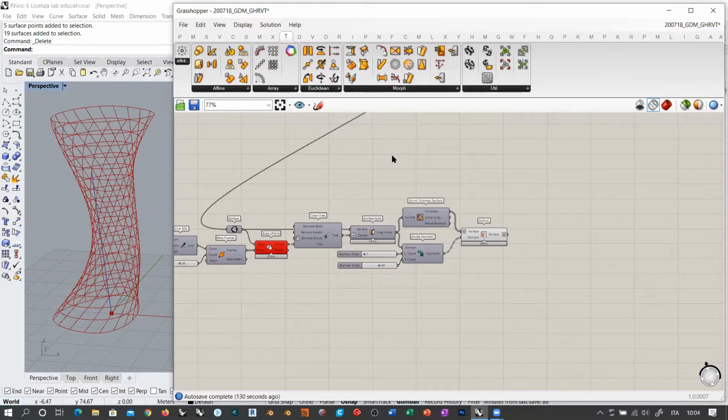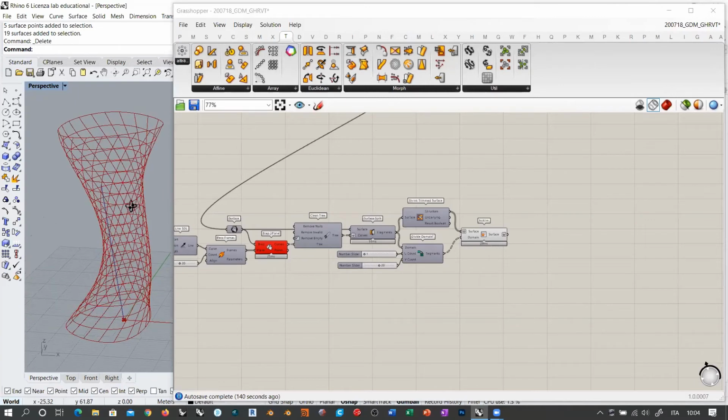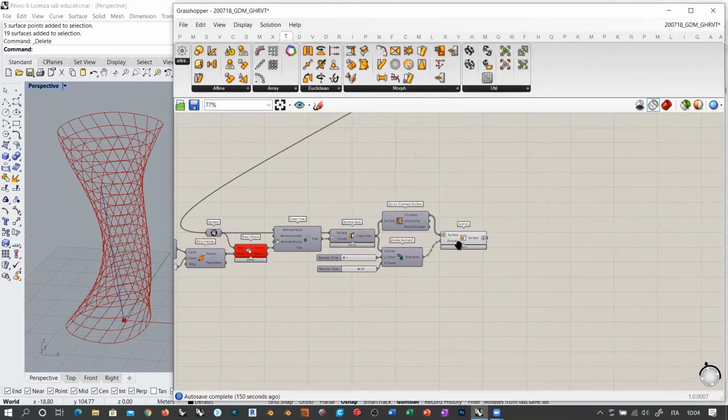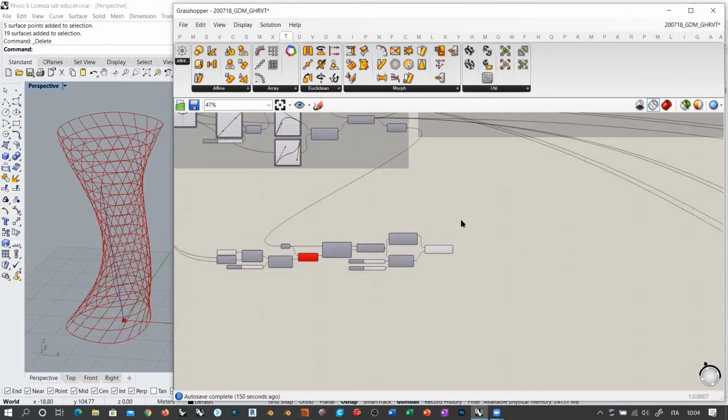They close or open some panels according to the level of solar radiation they are receiving, or simply light intensity. So you can do this easily in Grasshopper and then export it to Revit. The trick is always to create the most controlled geometry possible in Grasshopper. This also has to do with the Revit limitations that we were already discussing yesterday.